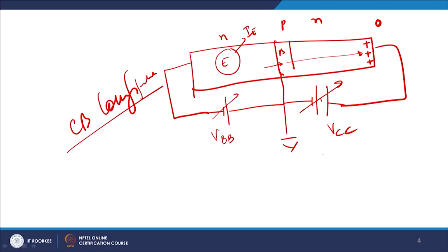Though we didn't apply any positive potential on the collector side, a current from the emitter side is still reaching the collector side in a very fast paced manner. The reason is that though a bias was not applied, the velocity is so strong that it can easily cross the base region and reach the collector side.